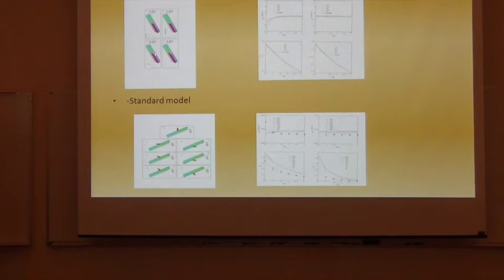But this model is called concentric, and we have gas inlet and air inlet situated on the same side. So it means they're all coming the same way from the same spot. And in his research he proved that this concentric model gives us the best mixture of air and gas.